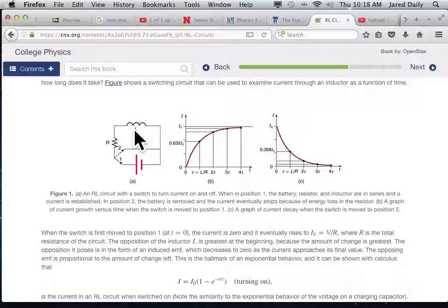In what part of the inductor? What did the inductor create that can store energy? Magnetic field, right? So when we started driving current through here, we started storing energy in the magnetic field that we were creating. When we turned it off, the magnetic field had a bunch of energy and it needed to go somewhere, and it went into driving that current around the loops more. So if we switch the switch from the battery to this place, the current will still flow. It will just flow through here, but it eventually dies off as the magnetic field dies off. And then it will go to zero.